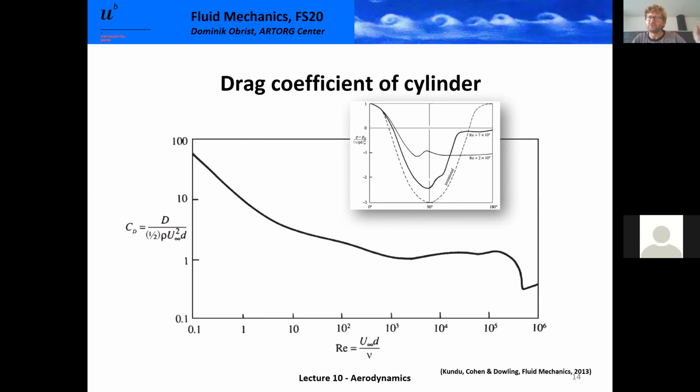Okay. So it's a weird concept. We are increasing the velocity a little bit, going beyond the critical Reynolds number, and the drag is dropping. This is the drag crisis. And I think we take a break now, a 15-minute break until quarter past, and then we look a bit at what this means and what applications there could be of this drag crisis.